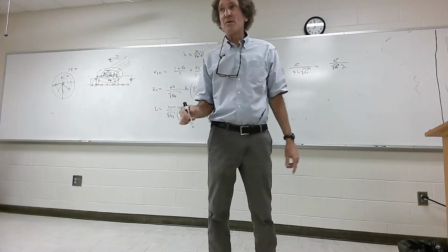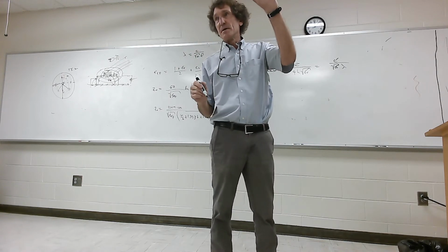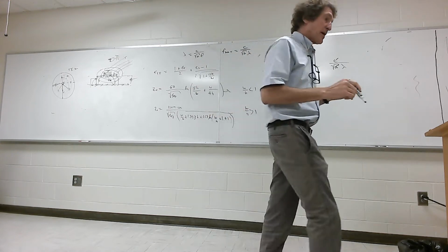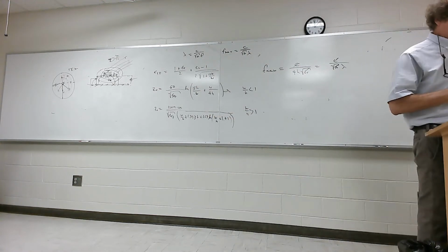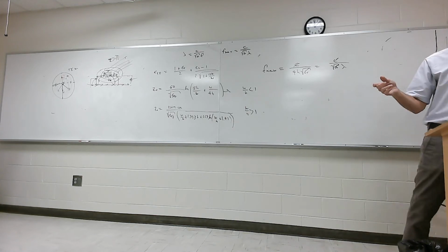So most of the time you don't even worry about that upper max, but you need to be aware of it if they're thick boards, especially if you're using high power microwave energy, because then you've got to be real careful not to get too near that maximum upper frequency. Y'all with me, class? All right, that's exposure to why we do what we do with these boards.